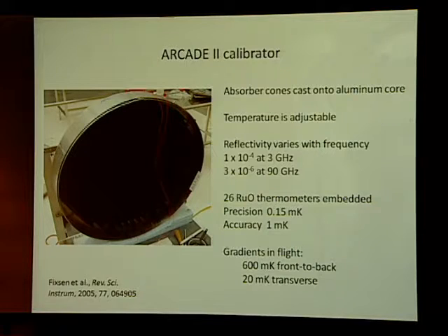This is a close-up of the calibrator. Again, this is stainless steel loaded epoxy. A whole bunch of little cones, with 26 ruthenium oxide resistance thermometers embedded in them. The thermometers are calibrated against a NIST thermometer to an absolute accuracy of about 1 millikelvin.